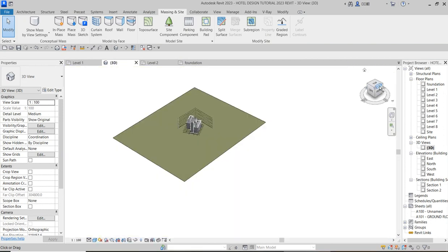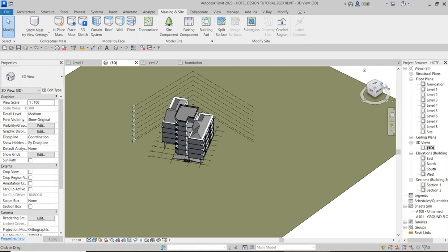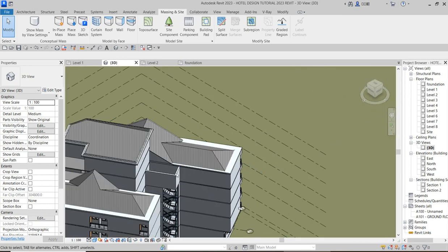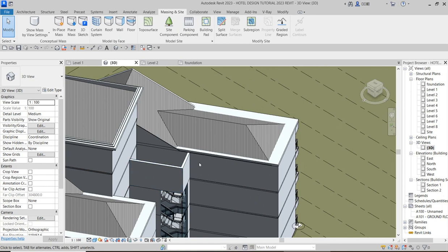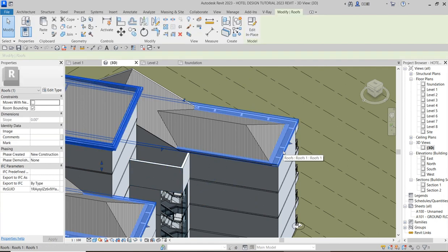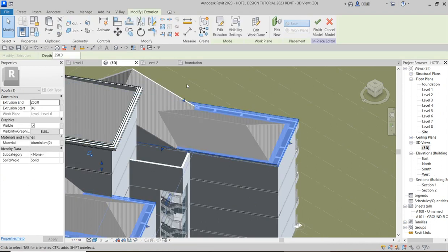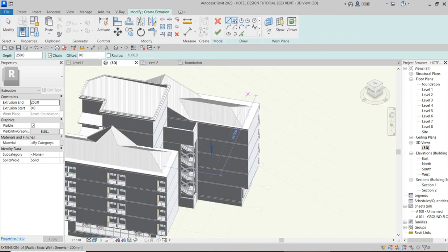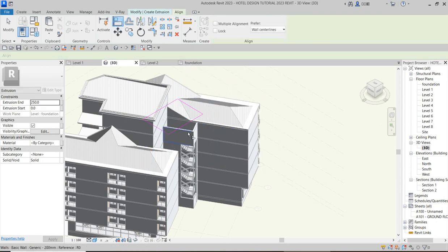So the next thing, you go back to that rotating part. No, we have not done a lot of work. We are not through yet in our design of this staircase point. So what we do is use the similar element we created here. So select, and we come here and say create similar. We want to draw it on 3D. We're selecting here. It's telling us history, but it doesn't matter. So what you just need to do is align it if you want to.